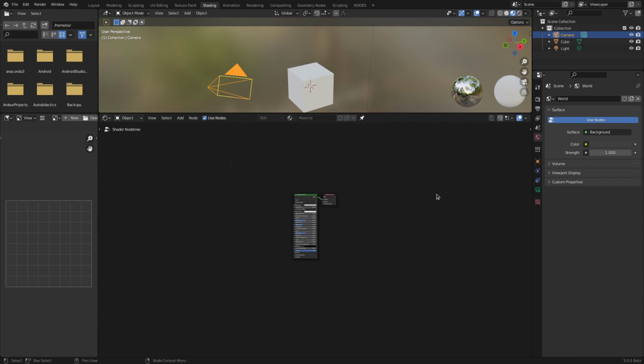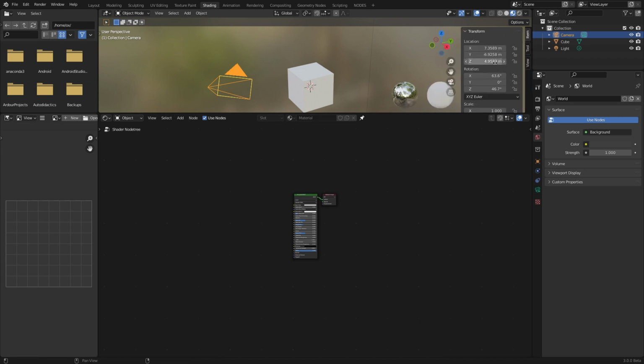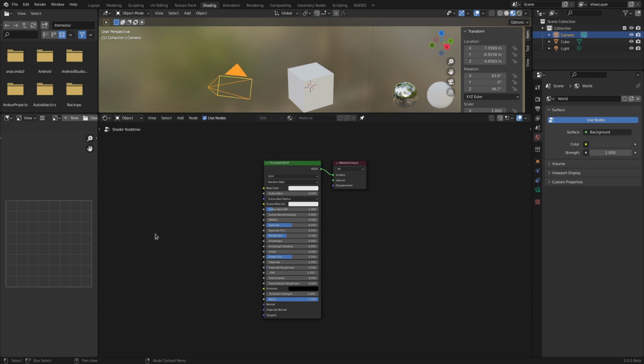If you remember, we were talking about this in the sidebar: holding Control and middle mouse click and pulling up and down zooms in and out. And how we got back to zoom 0, you simply hit the Home key and it brings it back to normal. It's the same thing in your nodes editor. The last thing to know: in the 3D viewport, the Shift A shortcut brings up the add menu, so you can add meshes that way. To add nodes, it is the same shortcut in your node editor. Shift A brings up the add menu, with your entire node selection type and all of the nodes you can add. Like that. And of course you can plug it into whatever and start having fun.